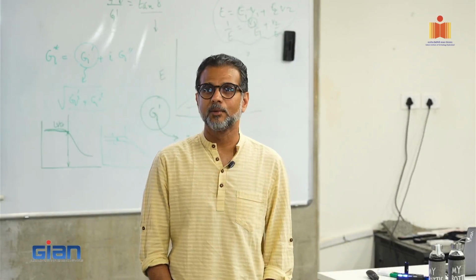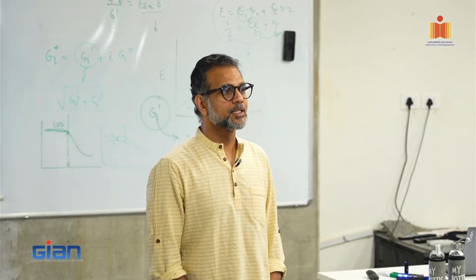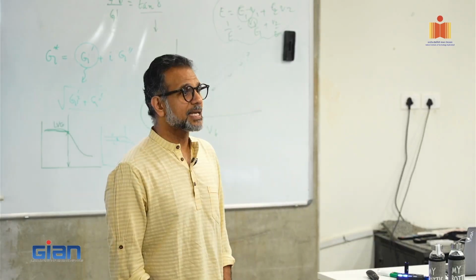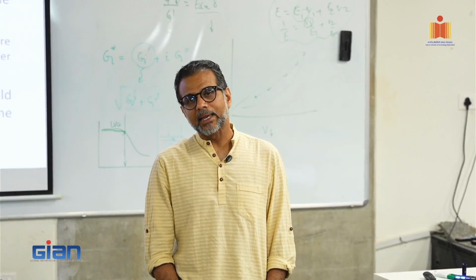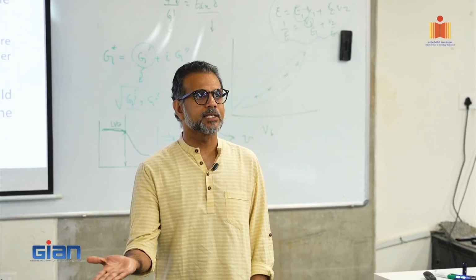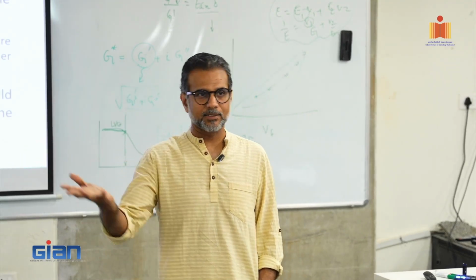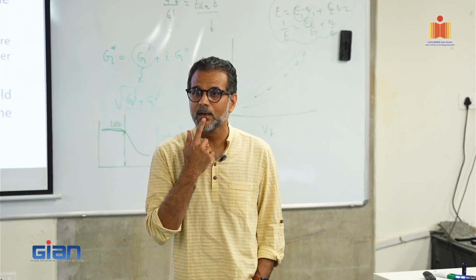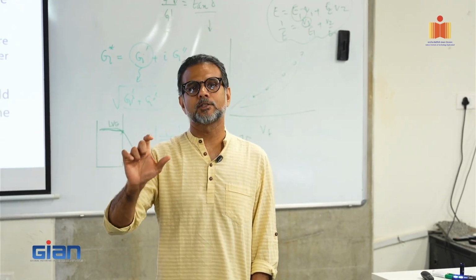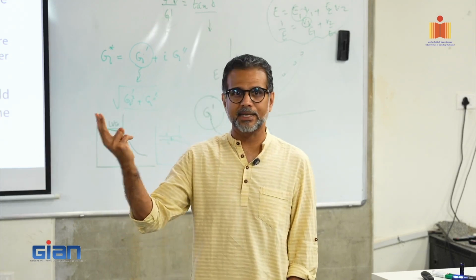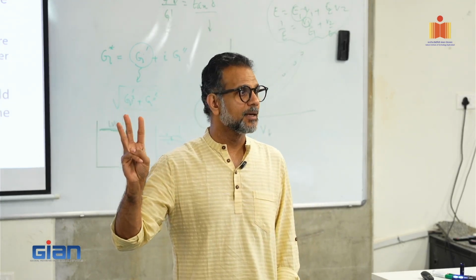Yield stress. How many yield stresses? Two. Why static? What will static tell you? It gives you an indication of structuration from rest. So it's a buildability characteristic. What will dynamic tell you? The ability to flow or the onset of flow. Okay, so two yield stresses. Great, everybody remembers that. What's next?